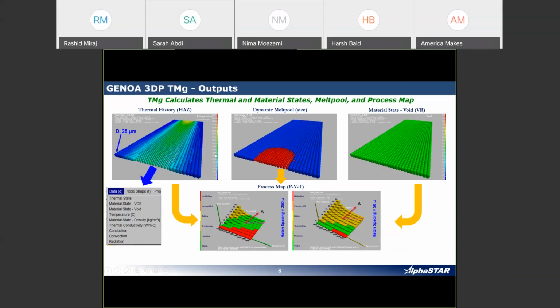And then this information compiled puts together, in this case, the parameter settings of power and speed versus temperature. It shows you the ideal regions to get the results that you want, the green area, and the areas to stay away from in terms of your parameter settings. Now, the color scheme here says this section is overheating, and this section is no melting. But the point being, it gives you a visual sense of are you in the right zone. And using my Goldilocks analogy, from Goldilocks and the Three Bears, this porridge is too hot, this porridge is too cold, and this porridge is just right.